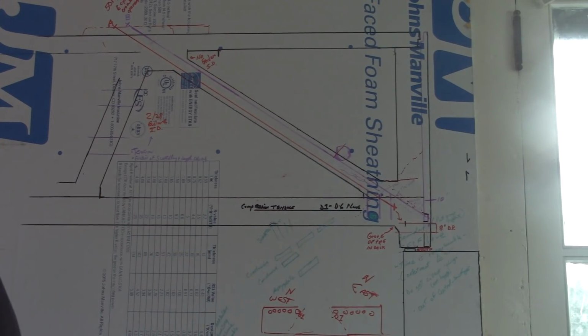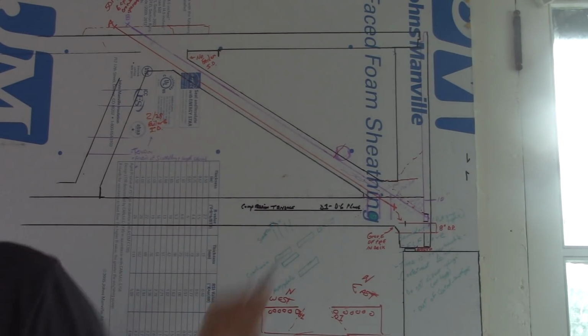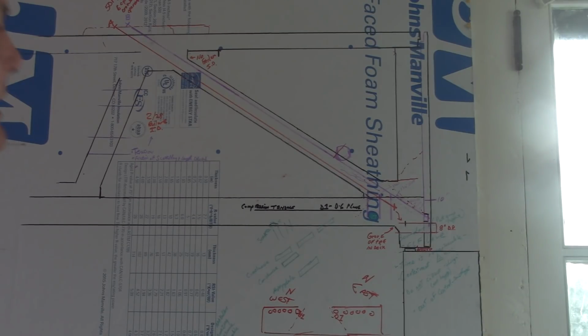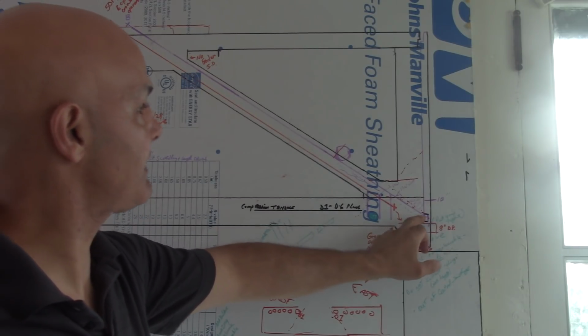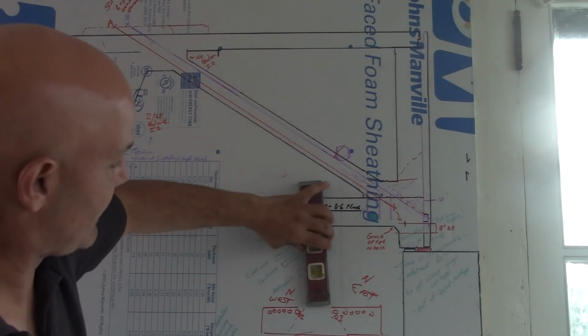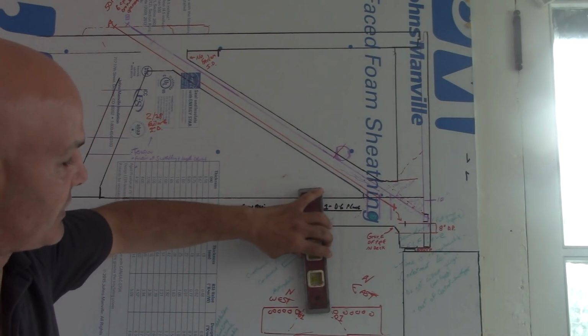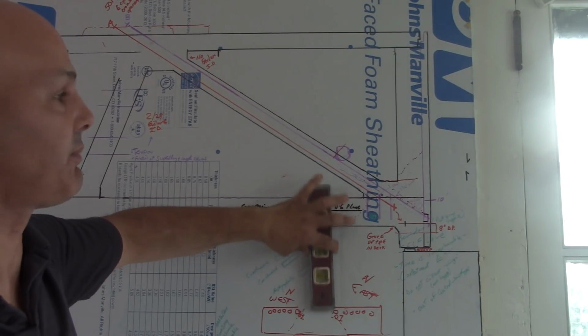All these cracks would be no big deal, except for, again, the load path is where they messed up. When this became loose and dropped down right here, it created this shear back here, which shows it's not structurally sound now. All the engineers should have known what they were looking at at that point.